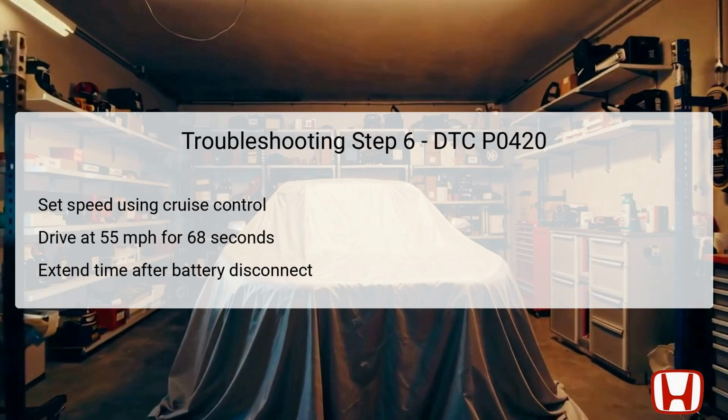If you've recently disconnected the vehicle's battery, this time needs to be extended to 4 minutes or longer. This extended drive helps wake up the system after a reset, ensuring that it's able to correctly monitor all relevant parameters. Always remember to drive under conditions that adhere to traffic regulations and environmental safety for accurate results. This careful approach maximizes the likelihood of diagnosing the root cause of the DTC P0420.